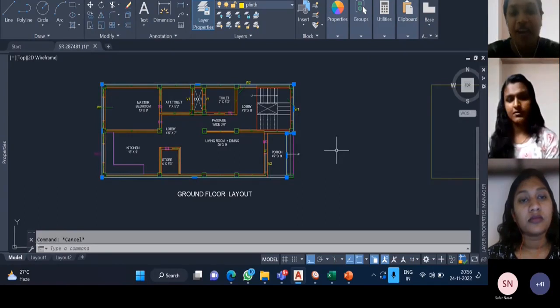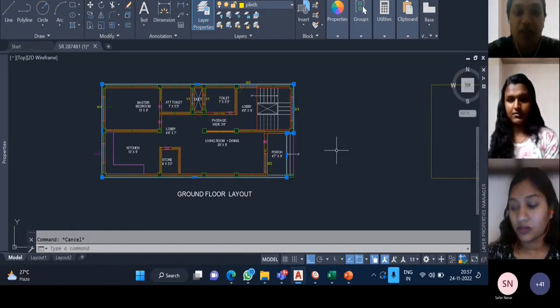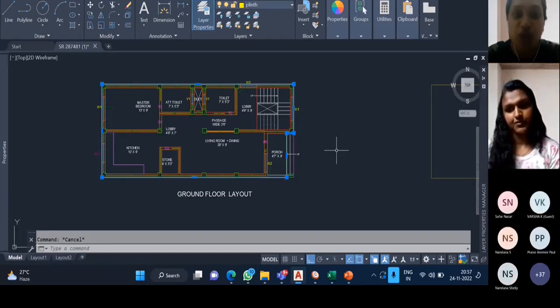For example, we may want to calculate the finishing of a kitchen platform, or the anti-skid tile provided, some random quantities which we won't get by direct scanning, like scanning the column and beam or doing the arc scan. These quantities we have to scan separately. So CAD utility is a tab where you can scan new quantities and create equations, based on which you can estimate the quantity.